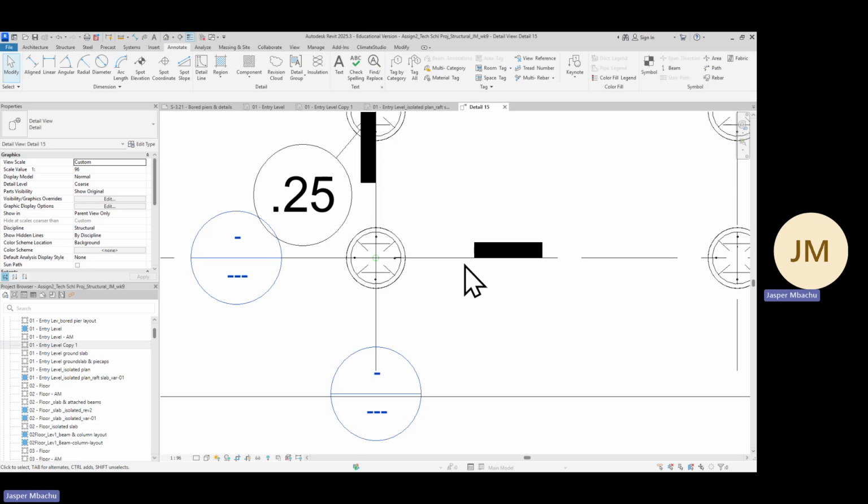Okay. Have you indicated? Have you put the two grid lines, I mean section lines, on that E and 0.5? So this one here. This is the one that we want to focus on. Have you put one section line and one section line below? If these section lines are there before, is this a section line that you put now, or were they there before? Then right click it and hide it, hide in view element,